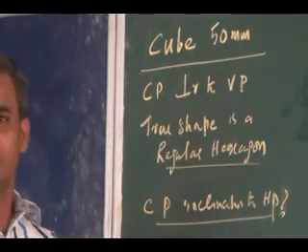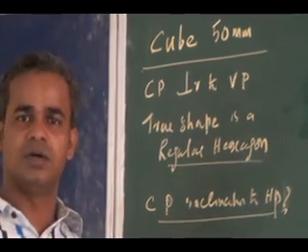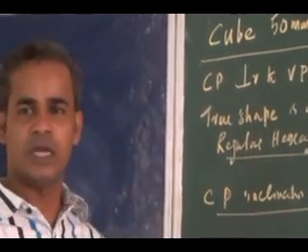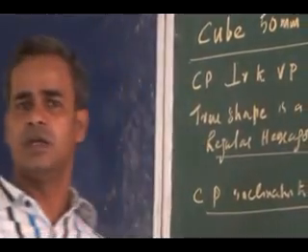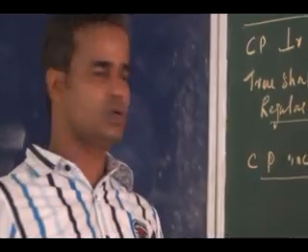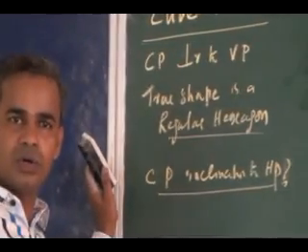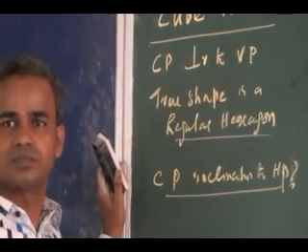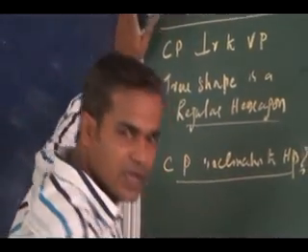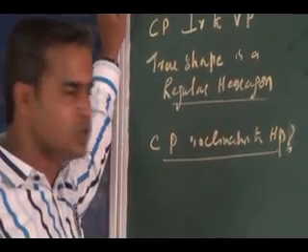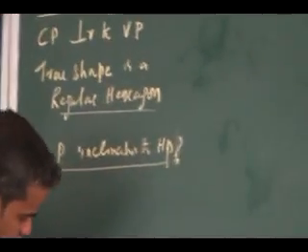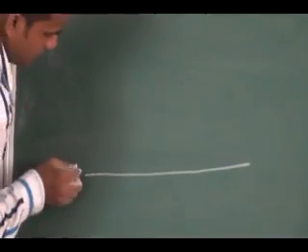So again, in this problem you can see the cube is kept with one of its faces on the ground and the vertical faces are equally inclined to VP. Since the cube is kept vertically, the vertical faces are equally inclined to VP. So where you have to draw the square of the cube, that is the face of the cube will be seen on the ground, that is the base of the cube. If I consider the two bases the cube has, then the base of the cube will be drawn on HP. So the reference line will be like this, right?